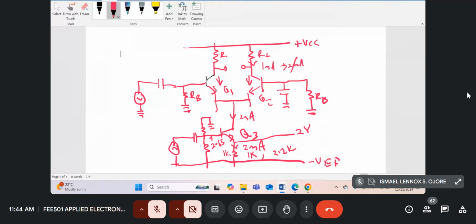I normally use 0.6 volts for silicon, but some of you are told to use 0.7. But you can check in the labs. So then you just have to design for the potential divider. Now this RB, let's call it RB2, and this top one, RB1. Now RB1 and RB2 depend on the input impedance, so the input resistance you want your source to see.